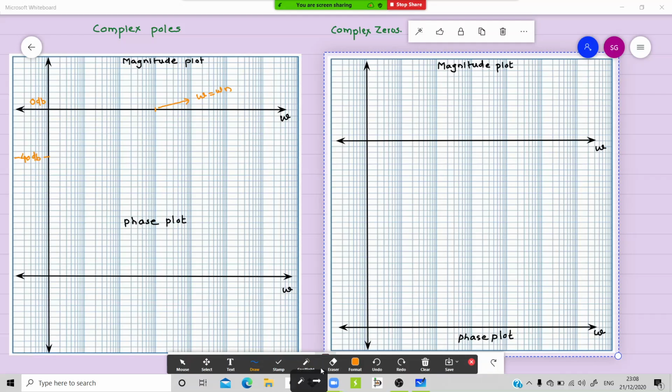Alright. So what we are seeing initially till this point, it is going to be a straight line. Okay. I am talking about the ideal case first, and at this point, 40 dB per decade. So this is the point through which it is going to pass, right? So you are going to have 40 dB per decade. So I'll draw that line also.